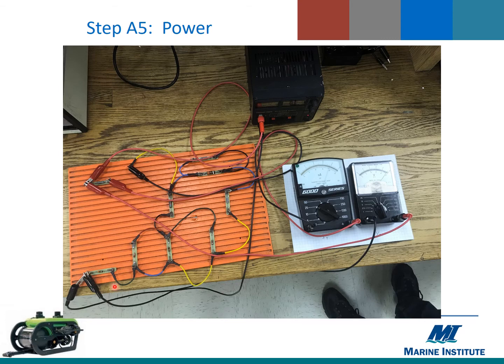Now, in order for us to get IT, we could measure the current going into R1, but because we got our voltmeter and power supply connected there, we broke the circuit here where this yellow wire used to be, and we allowed the current to go through this red wire into the meter positive terminal, out of the meter's negative terminal, and back into the yellow quick clip, and then to the remainder of the circuit. And once it hits here, it'll divide into I2, and it'll go this way, and it'll divide into R6 and R7. Okay, so the 2 meters here now will be set up to measure VT and IT.